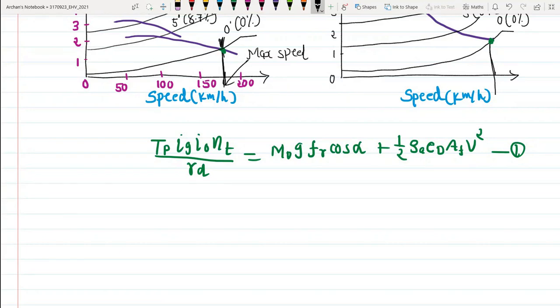Here it should be noted that for some vehicles no intersection exists between the effort curve and the resistance curve because of a large power plant or large gear ratio.